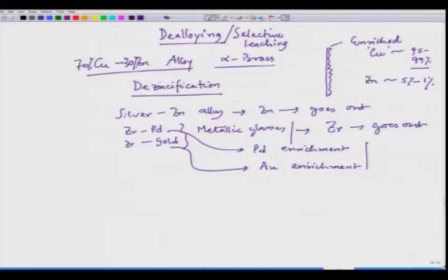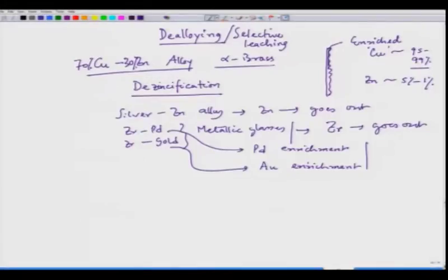This de-alloying is not good for some situations like brass. If we have a water pipeline designed for carrying potable water, drinking water, the inner wall of the pipeline can experience dezincification, the copper enrichment happens, and this copper region is loosely stuck to the inner surface.